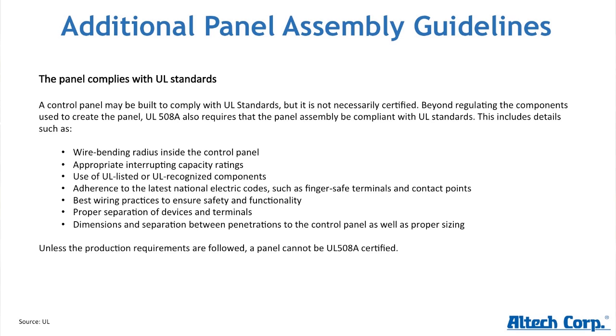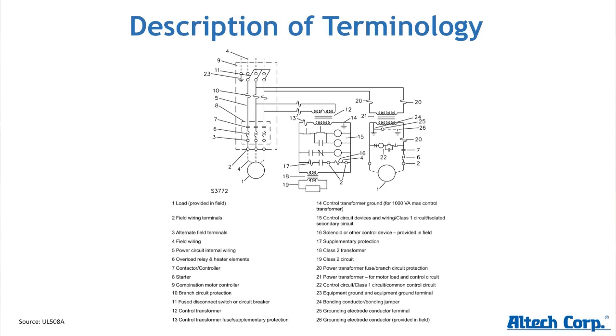It does not mean that you have a UL 508A listed panel. You need to use all listed components. I will go into that in a little bit more detail on the next slide. But everything is lined out in the standard itself.